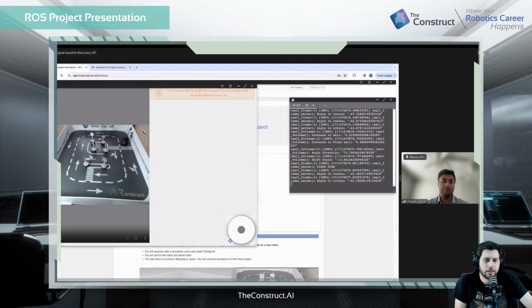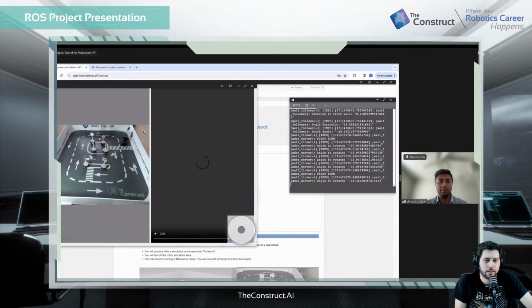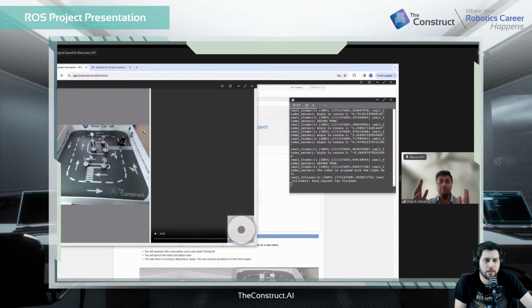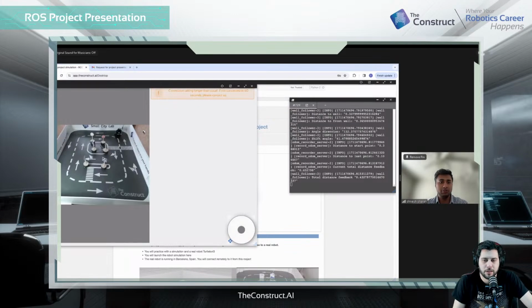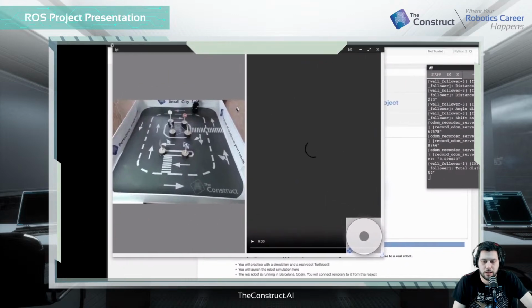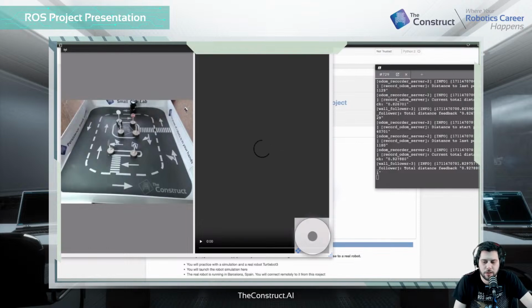Right now the robot is searching for the closest wall. After finding the closest wall, it goes a little bit behind to the optimal range. From there, it turns left so that the right-hand side of the robot is always parallel to the wall. And from there, the robot will start its wall following function. The robot has already started to move, and it is basically using two parts: the front laser and the side laser, or should I say the front right side of the laser.